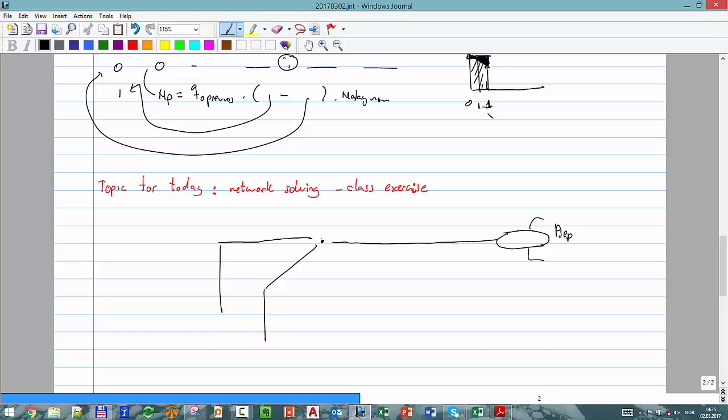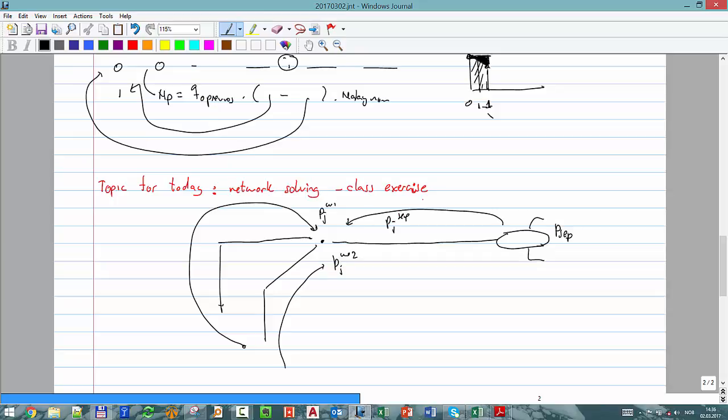I'm going to go co-current from the reservoir all the way to the junction, and for that I'm going to need the IPR equation, the tubing equation, and the flow line equation. From well 1 to P junction, then from well 2 to P junction, and then from the separator. All of them have to be the same.